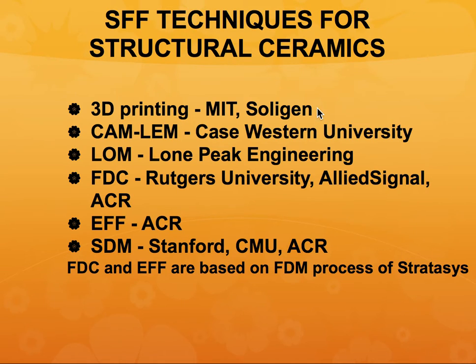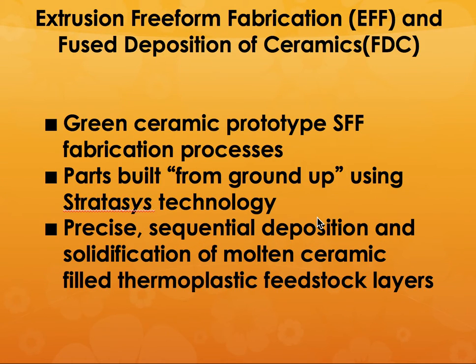You just inject some kind of a binder system that binds the powder particles together. This was originally developed at MIT and then taken over by an Israeli company called Soligen, mainly for shell molding processes for the foundries. And I'm not really sure if Soligen still exists or not.